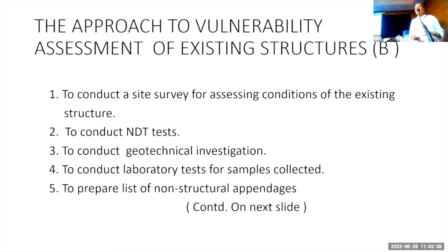So what is non-structural appendages? If it is a framed structure, only through the elements of the frame load gets transferred to the foundation. So we provide other elements for functional necessity. For example, this is a framed structure. I designed it as a framed structure. So here I have put that wall. That is for functional necessity. I considered the contribution of that wall in the load carrying capacity. I'll come to that a bit later again. These are non-structural elements. They are called non-structural elements, which do not carry load when I design my structure.